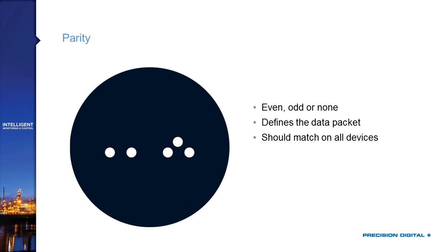I know that sounds kind of complicated, but let me try to explain it very simply for you, just so you have some idea of what parity does. Imagine that I've got a simple 4-bit word that I'm trying to send. That's 1010. Well, it's going to amend this, and it's going to say, all right, I have 2 ones in here, so I'm going to put another 1 on the end of this word, and that's going to represent the fact that I have even parity.